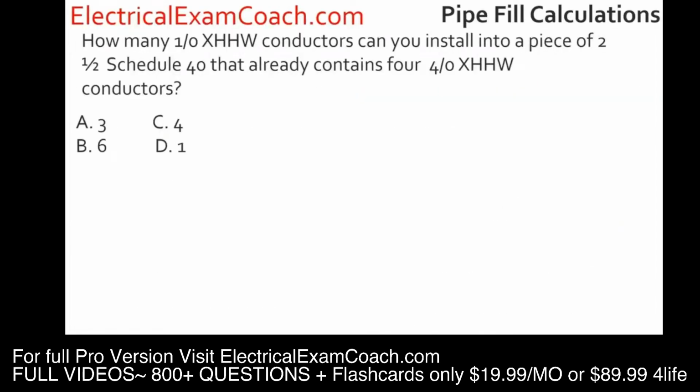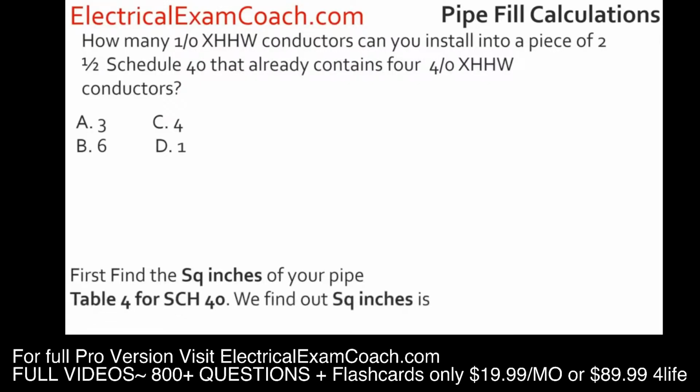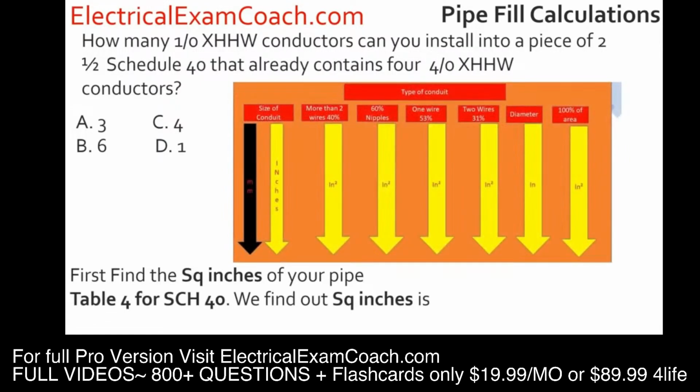How many 1/0 XHHW conductors can you install into a piece of 2.5 inch Schedule 40 that already contains 4 4/0 XHHW conductors? So the first thing we're going to do is find the square inches of our pipe. For that, we head to Chapter 9, Table 4, Schedule 40. When we get there, we first verify that we are in the right type of conduit. Then we come over to the left and find our size of conduit. Then we come over to the 40% column because we have more than 2 conductors, and we find that for this conduit, it's 1.878.